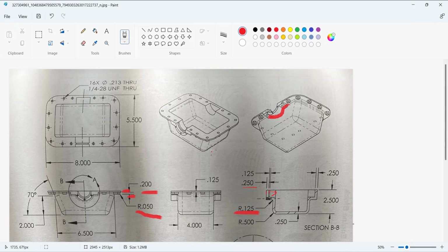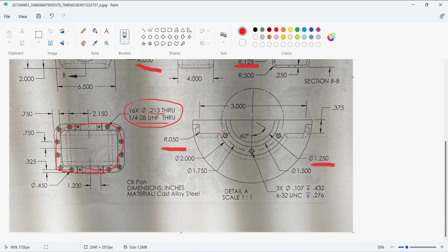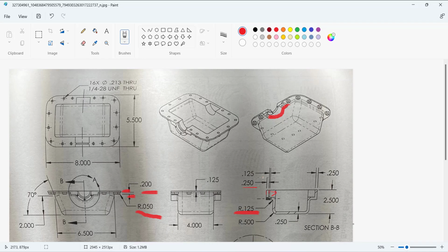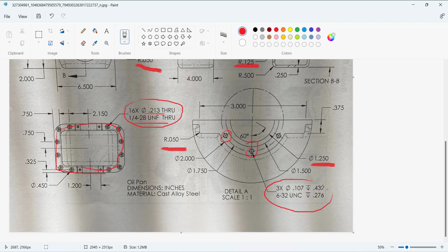Okay, next you can see we have some circular cut on this side, this one. Here you can see it's also defined the dimension of this one. So for this circle we are going to make the sketch on this tab and define this circle for the position of them, and then use the angle between 1 to 2. The other circle is 60 degree.